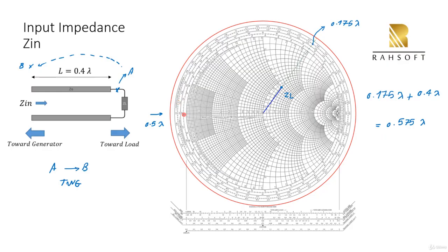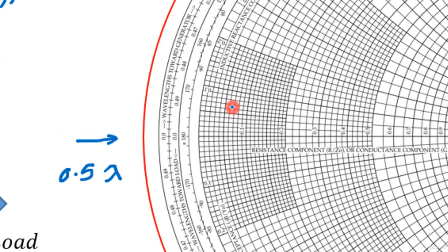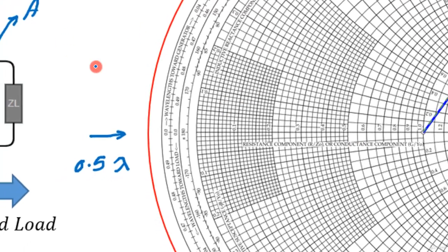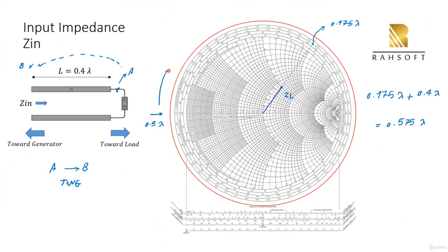But as you see, after this, there's no, for example, 0.51. It starts decreasing. This is how we show numbers on this Smith chart, but it doesn't matter. You can just find it. So it means that we have some kind of portion here. We have to go this portion, and we can calculate this portion, because as you see, it's decreasing from 0.5. It goes 0.49, 0.48. So what we have to do is just calculate this portion, and you can find it like 0.5 minus what is left here.